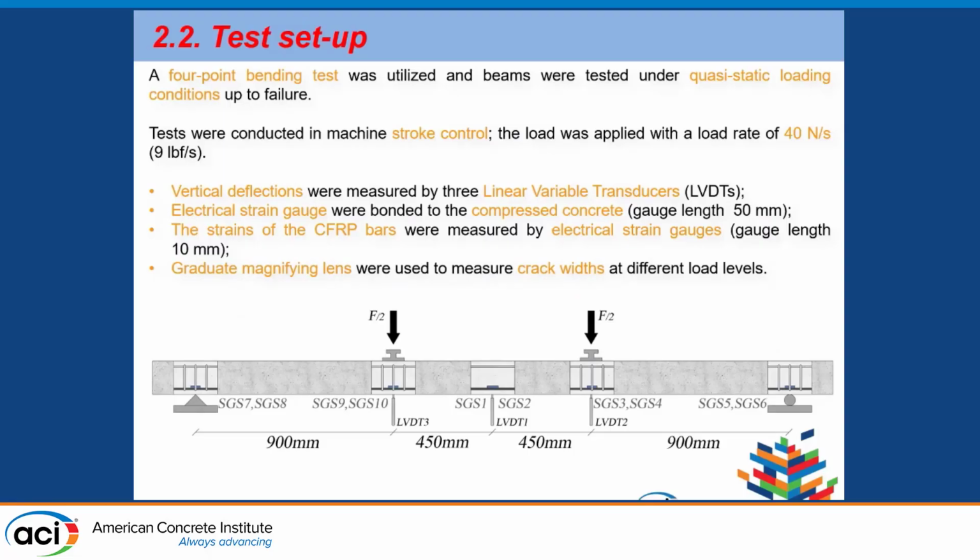Here, you can see the setup. As I mentioned in the previous slide, the flexural tests were performed under a 4-point bending configuration, and tests were performed until failure, using a load rate of 40 Newton per second.